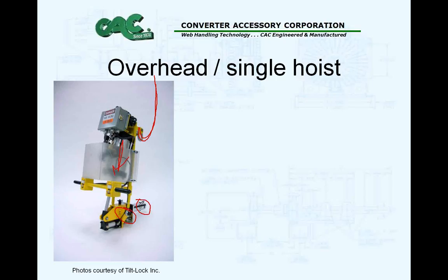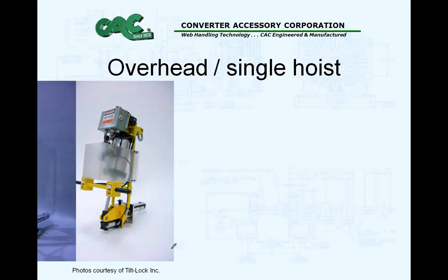So here's your probe teeth, and you would load this system into the core, and the teeth would come out, grab the core, allow you to get the roll up in the air, and then this actuator, I think this one is electric. This electric actuator allows you to pivot the roll 90 degrees. So this gives you the swiveling at this pivot point of 90 degrees.